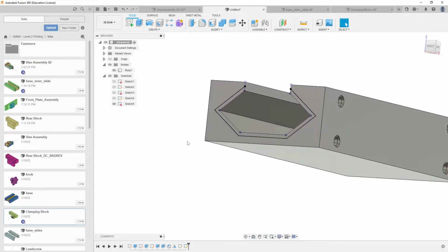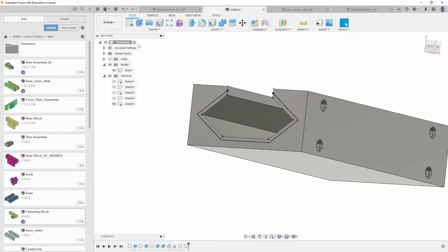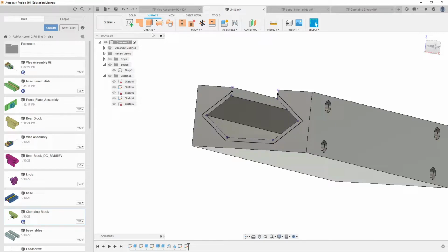We exit out, and then we have to do a different type of extrusion, and this is part of surface design. So now we're leaving this area here with all the tools that we've been learning right up here. We go now to this tab that says surface, and it has a whole lot of other things. We're going to use it for basically one element, and that is the extrude, but it is the surface extrude. This extrudes single lines, whereas anything extrude in solid modeling would not do that. So this is very helpful to know in many different cases.